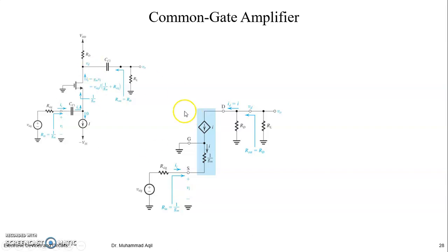Okay, so now replace this transistor with its model. Then the gate is ground as far as the AC equivalent circuit is concerned. This will behave as ground for the AC signal. RL at the source, we have a capacitor which will be short circuited for the AC signal, and R signal, right? So now if we find the current from here, then that current multiplied by the resistance with a minus sign will be given out.